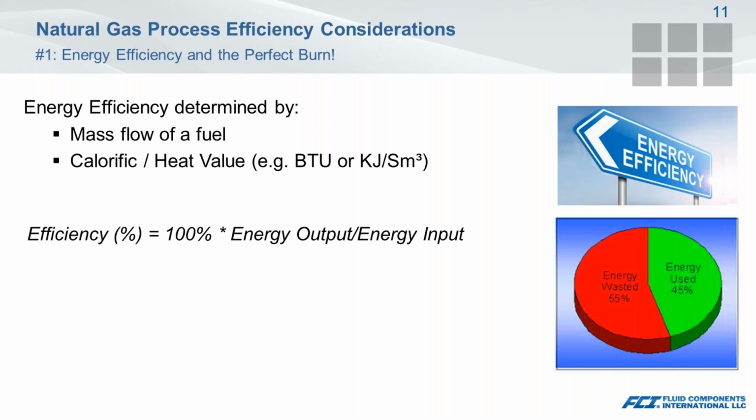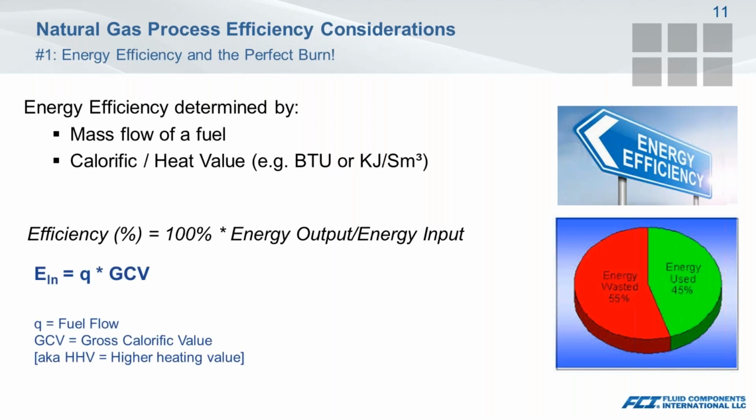So as we look at the efficiency based on the energy input versus output, trying to achieve that 80, 90, 100% value, we can look at a boiler as an example. Here we have the energy in being our fuel, our natural gas, and basically we're looking at the lower heating value or lower calorific value as a measure of available thermal energy produced by a combustion fuel.